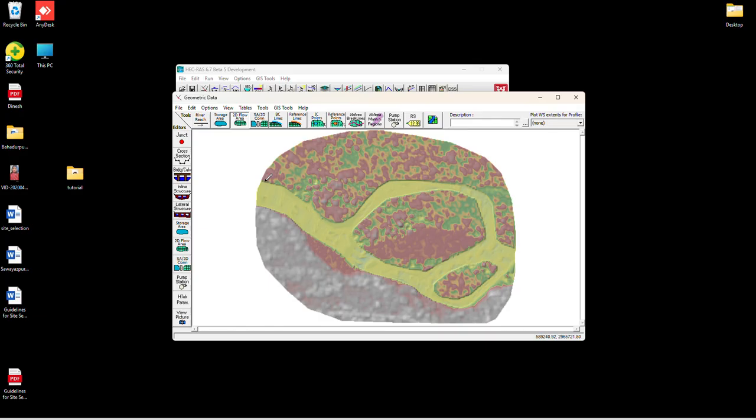So when you click 2D flow area, you have to start from left bank. This is a thumb rule, you have to start from left bank. To do anything in this modeling process, you have to start from left bank. Like in life you have to do everything from right hand, but in modeling, in HEC-RAS modeling, you have to do it from left bank. Model will understand the flow direction by this. So our flow direction is from upward to downward. So from where I have started, this digitization is from upstream direction.